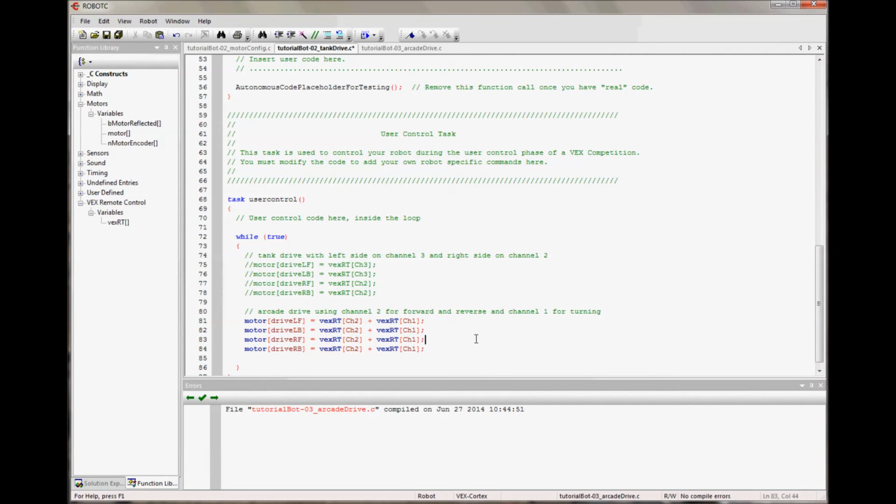So if I want it to turn right, I have to imagine what signal I'm sending to the motor. On the left drive, if I want to turn right, I push the paddle towards the right, which is a positive number, which makes the left drives go forward and turn towards the right. So that's correct. I'm adding the right component and it's going right.